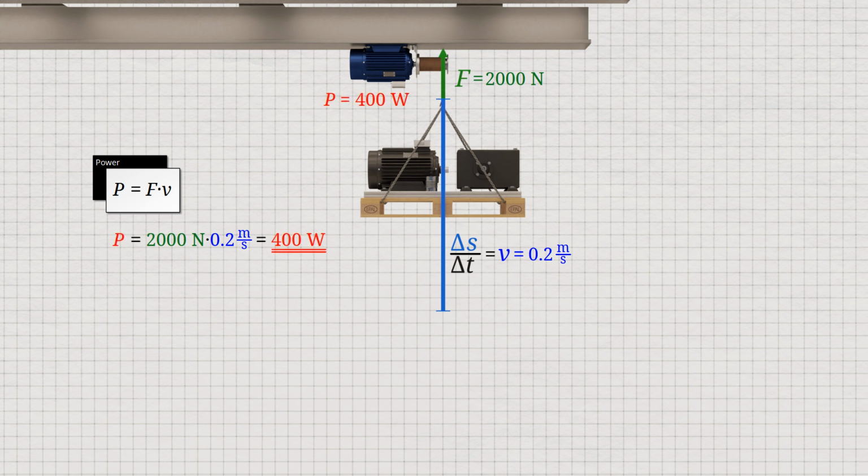If the friction of the rotating winch is neglected, this corresponds to the required motor power, as the motor must ultimately deliver this calculated power to the lifting load. If a greater load is to be lifted at the same lifting speed, more motor power is required. However, motors cannot provide an unlimited power. If only a certain motor power is available, it is clear from the formula just derived that a higher force can only be achieved at the expense of speed. A heavier load can therefore only be lifted with greater force if the speed is reduced accordingly.